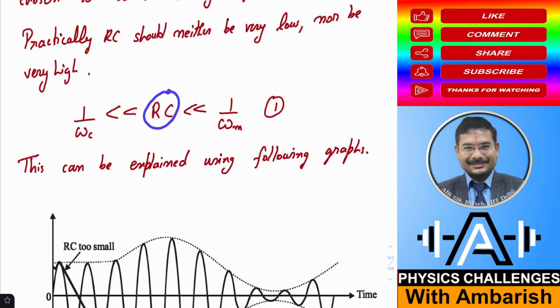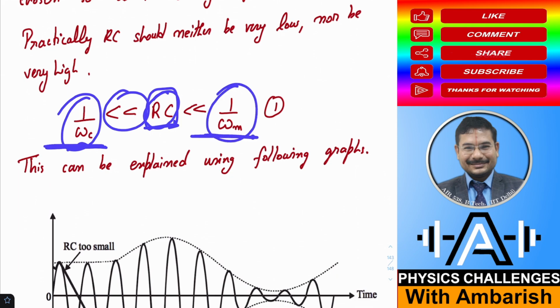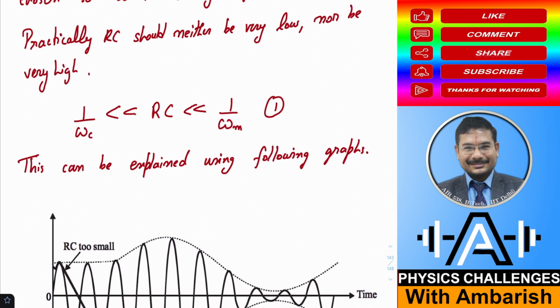That the time constant of the RC circuit should be much greater than the time period of the carrier wave, and it should be much smaller than the time period of the message wave. All of you know that carrier frequency is very high, generally in megahertz, whereas message frequency is generally in kilohertz. Time periods are inversely proportional to frequency. So that's why I said that the time period of the RC discharging circuit should be much greater than the carrier time period, and much smaller than the message signal time period.